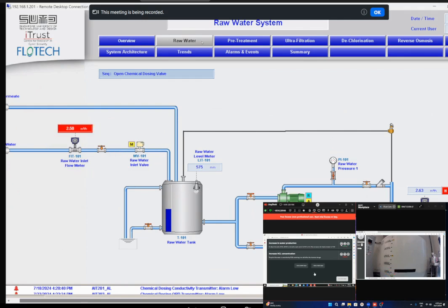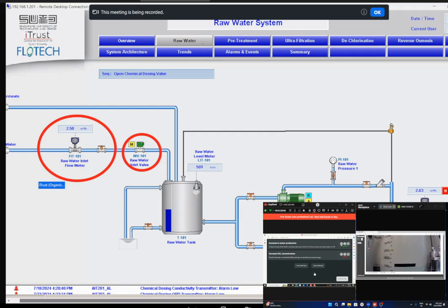So as we can see, the valve has been turned to manual mode, and the red valve is currently turning green, and the flow meter is also showing 2.5. Now we'll see the LIT101 value stabilize around 569 because there's water flowing in, which is much higher than the water flowing out. So we'll see a gradual rise in LIT101's value because the pump is also simultaneously trying to pump out the water.